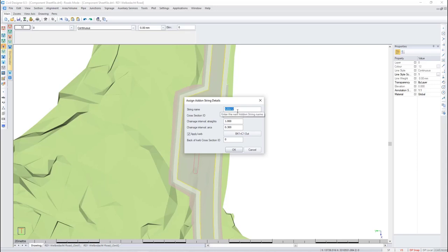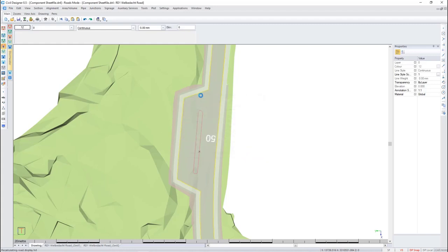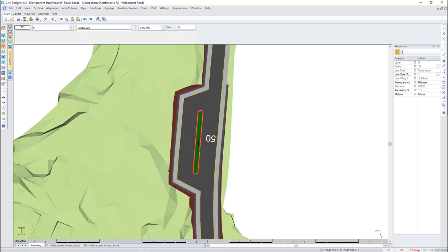So we're going to call this bus island. The reason it shades it is because there might be CAD entities underneath the road which you'd want to be selecting. Good, so it will ask us if we want to indicate another polyline. I'm just going to press escape, and now we've got our island here.